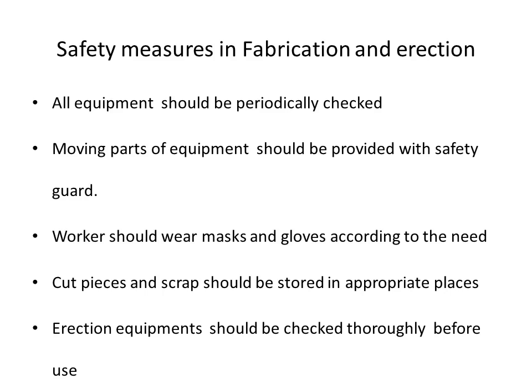The workers engaged in erection work should wear helmets, safety belts, etc. All erecting equipment like hoist, crane, etc. should be thoroughly checked before use.